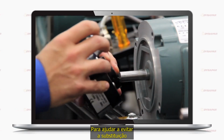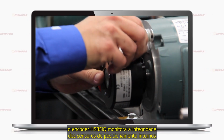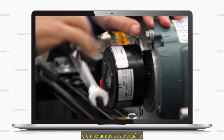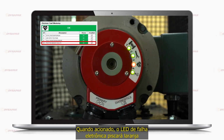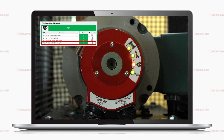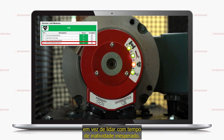To help prevent the needless rip and replace of a functional unit, the HS35iQ encoder monitors its internal position sensor's health. This feature tracks the health of the internal LED within the position sensor and issues a warning to the user when the LED is nearing the end of its life. When tripped, the electronic fault LED will pulse orange, indicating that the encoder is still operational but will need to be replaced soon. At this time, maintenance should be scheduled to replace the encoder before the encoder malfunctions. This will ensure maintenance during scheduled downtime rather than dealing with unexpected downtime.